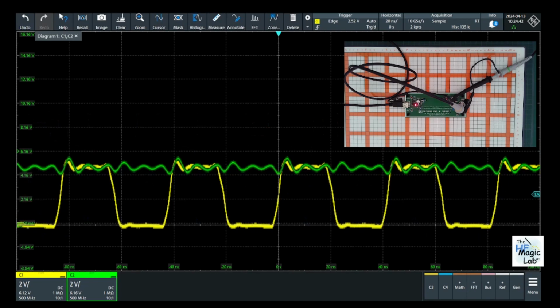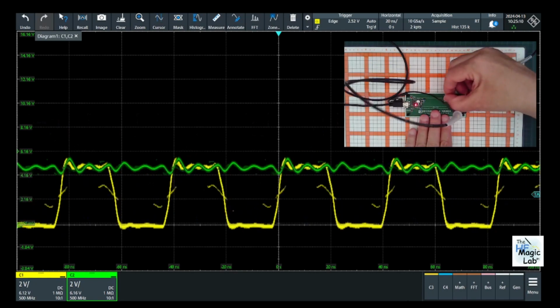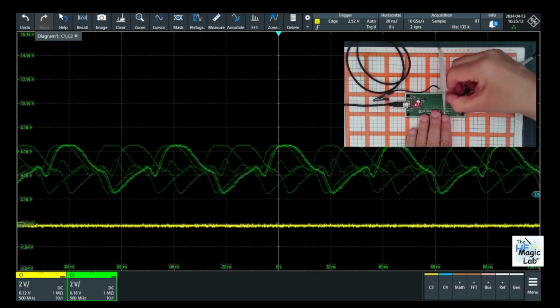So as I explained before, this is a typical solution for the signal and power integrity world. Remember that I am using pigtails, so the signal is totally clear, and because I am using jumpers, the inductance of my decoupling network is not optimized. But how is the effect of this decoupling network in EMI? To do this, let me deactivate the decoupling capacitor again.